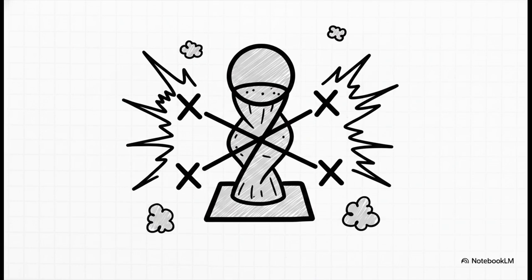Now, a quick word of caution when you're blending complex profiles using the loft tool. We've all felt the pain of trying to loft a shape across multiple planes, only to get this twisted, mangled result that just crashes the software. Why does that happen? Because our guide points were crossed. Always ensure your orientation points line up smoothly across your sketches. Otherwise, your loft is going to twist into a totally failed mess.